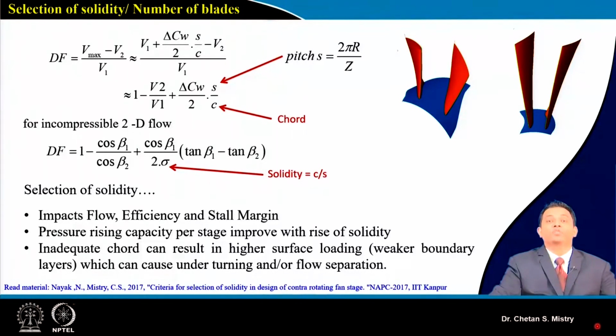The reason is that we have so many expectations from those gas turbine engines, and we are looking for those engines to work perfectly. When we talk about engine application to aircraft, as we discussed, we are looking for compactness, light weight, and highly efficient engines with a wider operating range. To meet such requirements, the per stage pressure rise expectation increases. That means the stage needs to do more work, and that's where our selection of parameters comes into the picture.